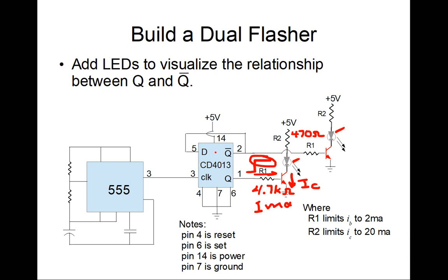Now, setting up the flip-flop means we have to provide power here. We have to disable two features of the flip-flop, called set and reset, so we ground both of those. We just wire the two pin 3s, which is just a coincidence between the 555 and the clock. And then we take the complement of the output, or Q bar, and run it back into the input, so it changes state every time the clock goes high along here.